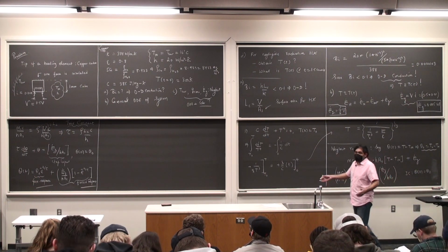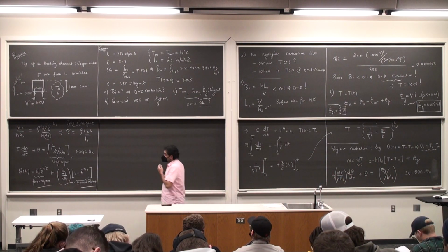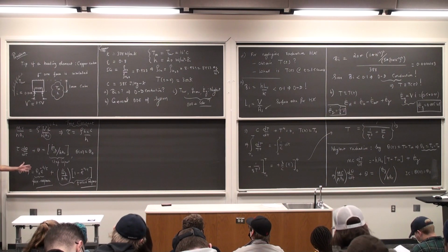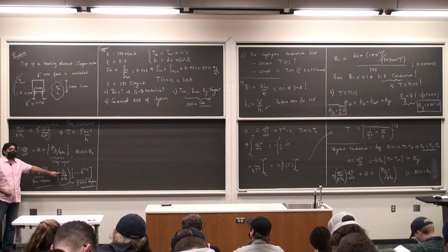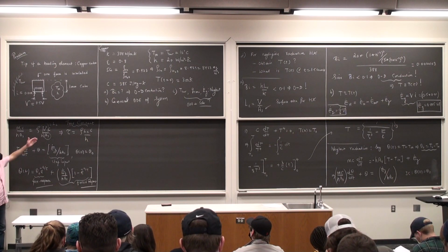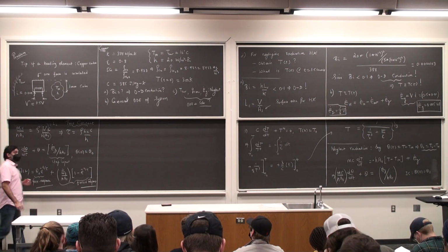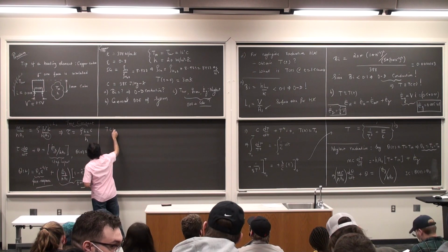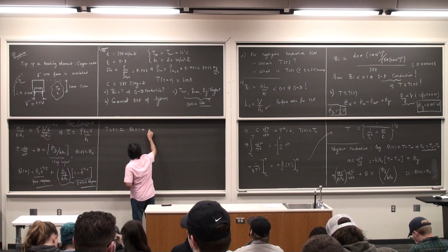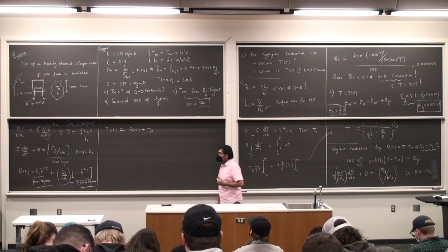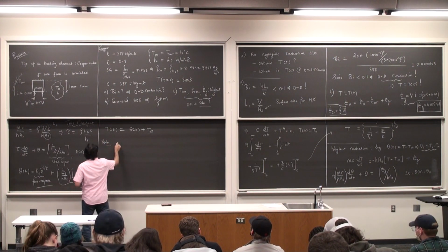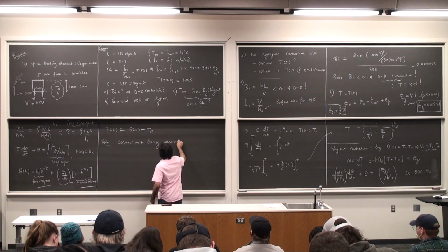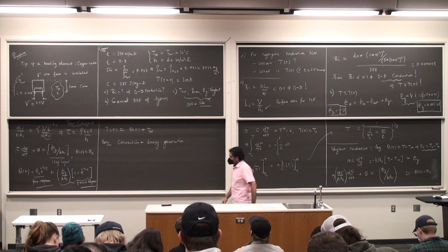But this is generic, so for any kind of a system that we are studying in transient conduction, which is zero-dimensional conduction, if I have convective heat transfer, if I have energy generation, this is my solution. That's it. Don't need to do anything else. If I have negative energy generation, this becomes minus Eg. If I have positive energy generation, it's plus Eg as written here. Tau is the same character that we have found out there. Substitute. Be careful, theta is the change of variables that you've introduced. So if you really want the temperature of the cube, T is theta of t plus T infinity, so please be careful there. So that my final solution for convection plus energy generation, my final solution is the following. So T of t.